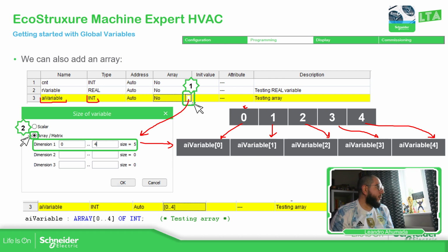If we are going to create, for example, motor current, an array, we should be able to have an array of motors, and all of them is going to be the current. So we just need to define the correct array. This is useful, for example, when we work to easily exchange information on an HMI. We have our image of the element, and we just change the index. So only the data is changing, but the visualization isn't.